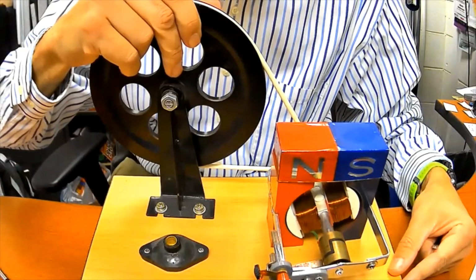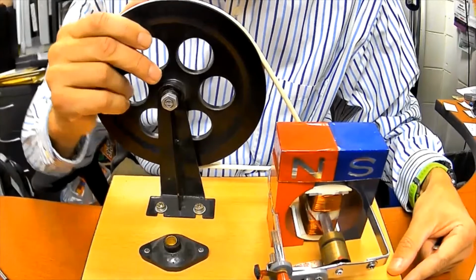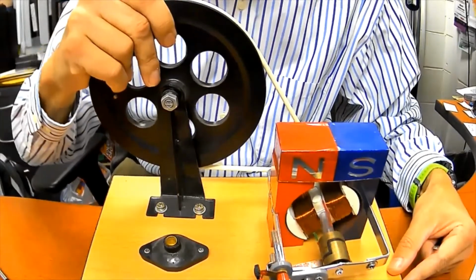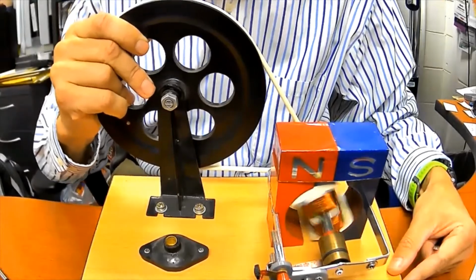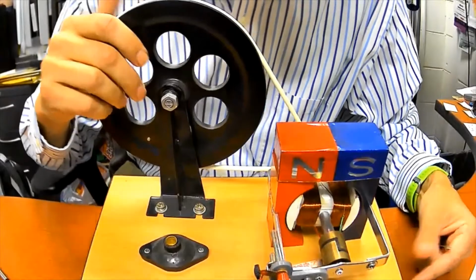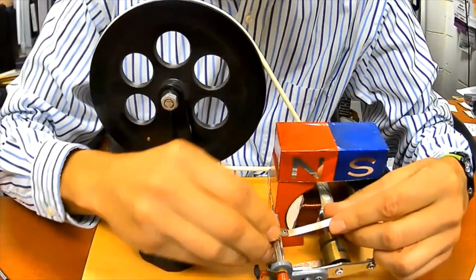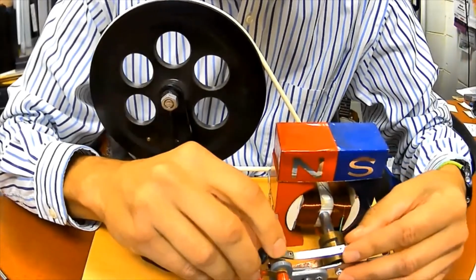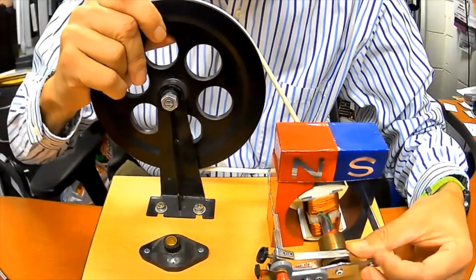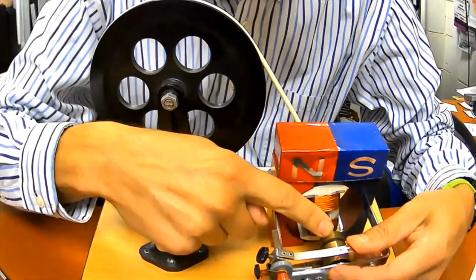All right, so you see how it's kind of split into 2 in kind of a strange way. And the way that it is designed, you can actually make this work like an AC generator. And if you want to make it work as an AC generator, then you put one brush all the way on one side, say over here, and now it's going to rotate around. And you put the other brush all the way on the other side, so over on here.